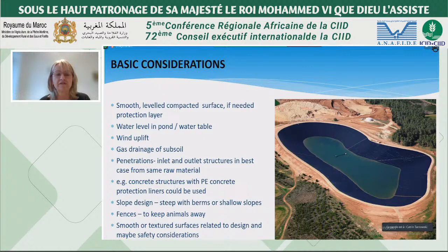And penetrations, the inlet and outlet structure, as we had heard from Professor Giraud already, are a critical point in the design and should be considered carefully. It is of advantage using something with the same raw material. For example, concrete structures can be lined with polyethylene concrete protection liners.